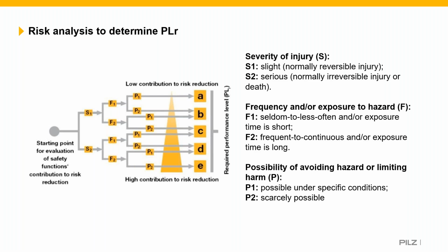Again, if we reference 10.218 part 2, they give you, as a C-type standard, a specific value. They say if the robot is moving at less than 250 millimeters per second, then you can claim avoidance. Funnily enough, the maximum teach speed of a robot is 250 millimeters per second because you'll need to be in the cell with the robot generally to teach it, or quite often. So that's why they've given that value.